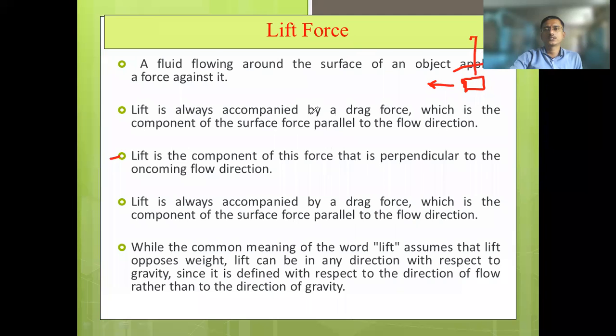So lift force is always accompanied by drag force. Drag force is continuously there. When the lift force is there, the drag force is also acting on it. Okay, which is the component of the surface force parallel to the flow direction. Lift is the component of this force that is perpendicular to the oncoming flow direction. The force acts perpendicular to the flow direction.